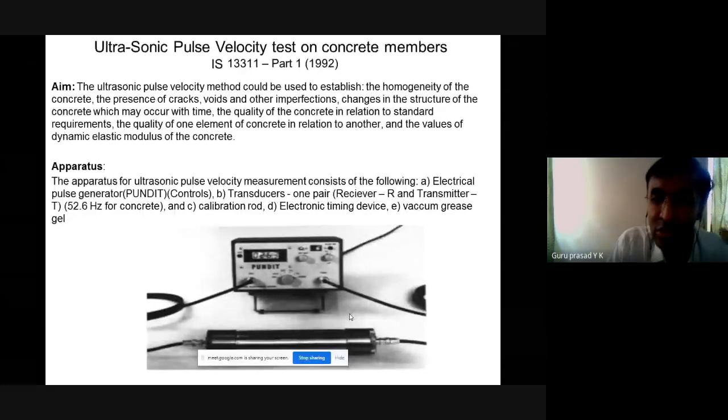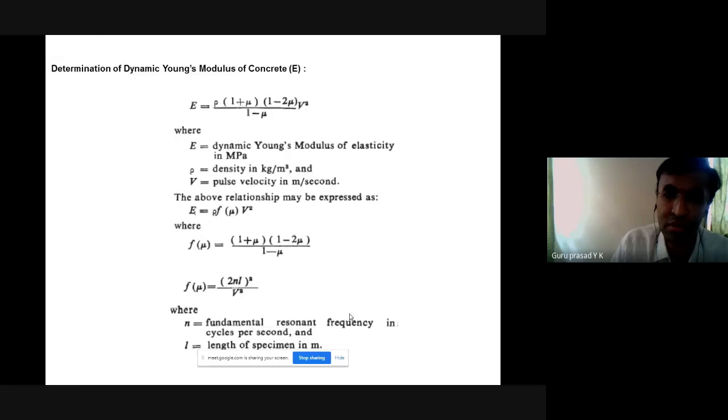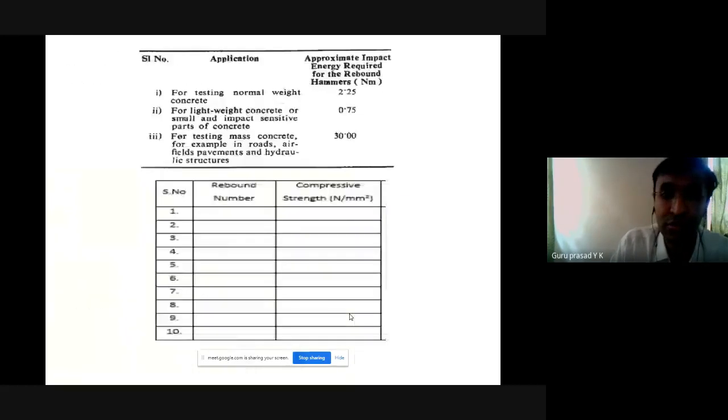If you drop these probes and the piezoelectric crystal inside gets damaged, your probe becomes inactive. It will not be usable at all. So please be careful. It is most important that the crystal inside should not get damaged by impacts or dropping.